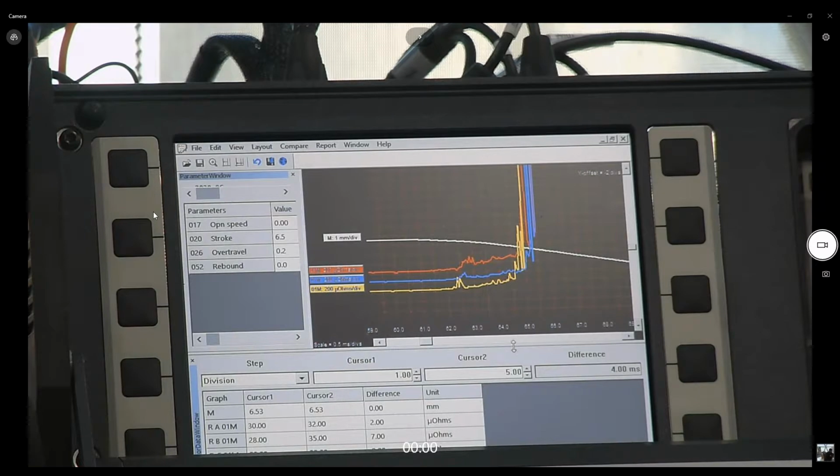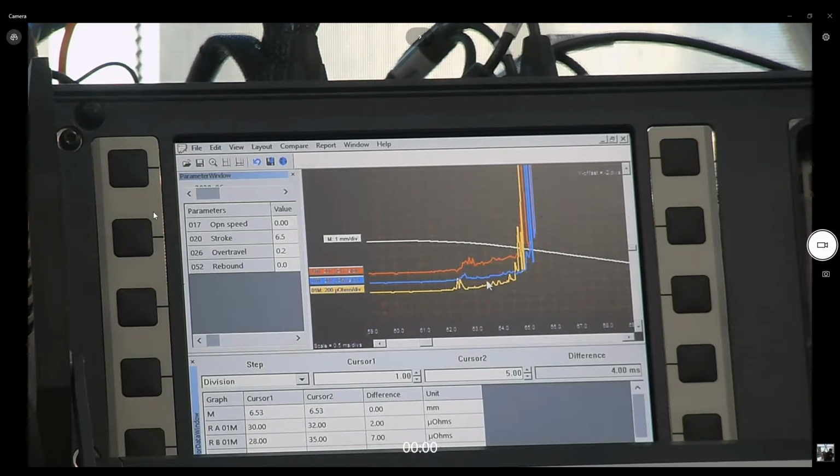That's why it is important for me to measure these two values. As I mentioned earlier for you, this is an air circuit breaker, not SF6, which has two contact systems, same as I showed you on the slide. Unfortunately, I don't have something like that in the office where we have to showcase, but still, it can give me a similar result. And you can see a slight jump here before going to the open position, and from that I can measure my arcing contact length in comparison with the motion test.